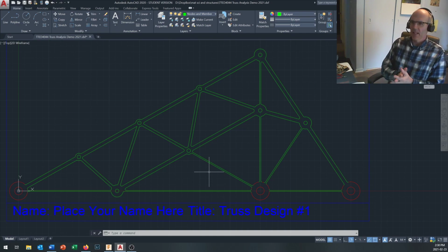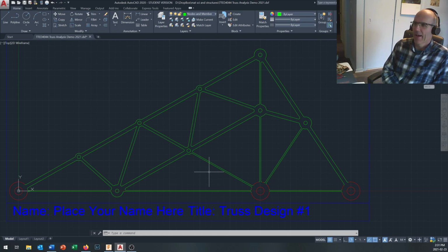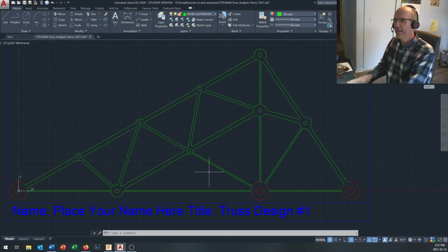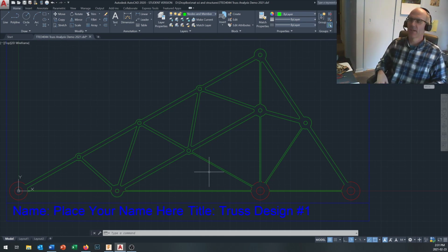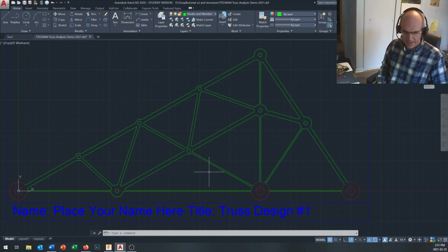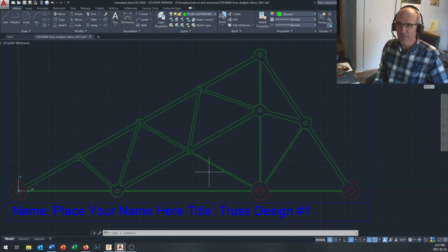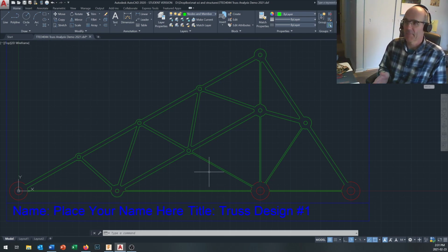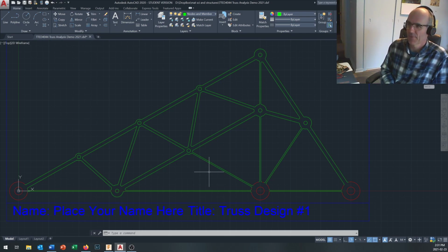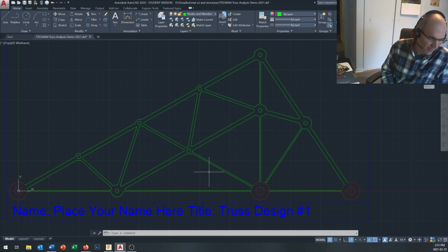Now, in a previous lab, I asked you to measure the mass of a chunk of MDF and also to measure its size. And if you did that, with our 18 by 24 sheets of MDF, I forget exactly what they weigh, but the density came out to 0.9, which makes sense and matches all the predicted properties for MDF. So 0.9 grams per cubic centimeter, or a specific gravity of 0.9.